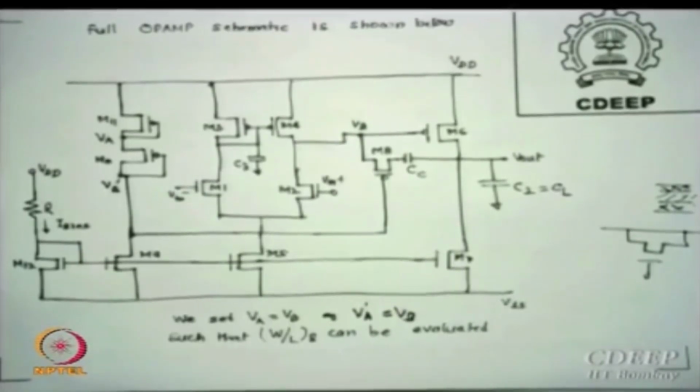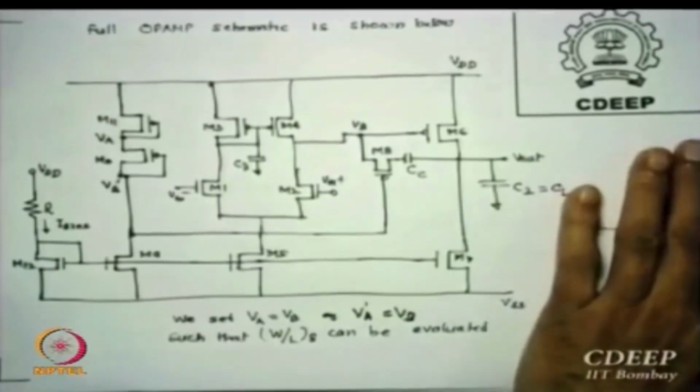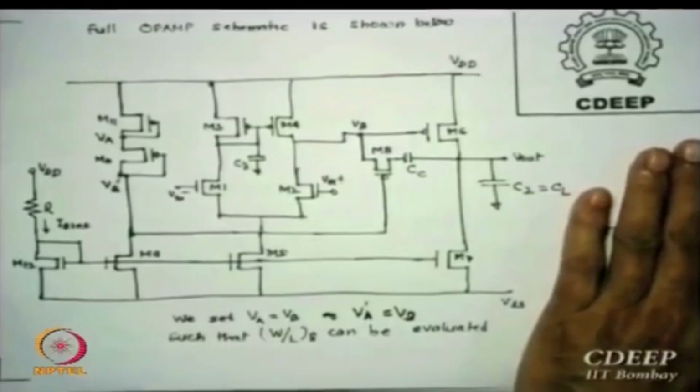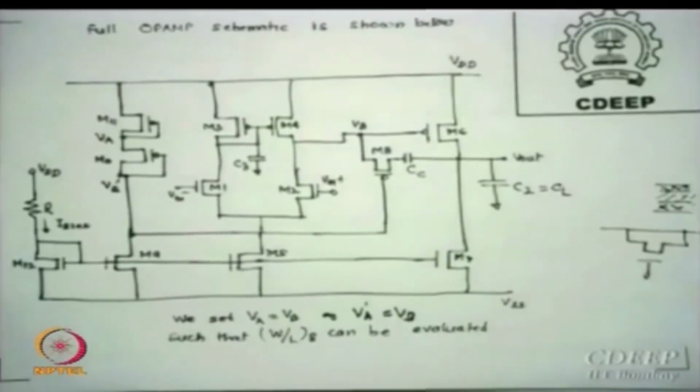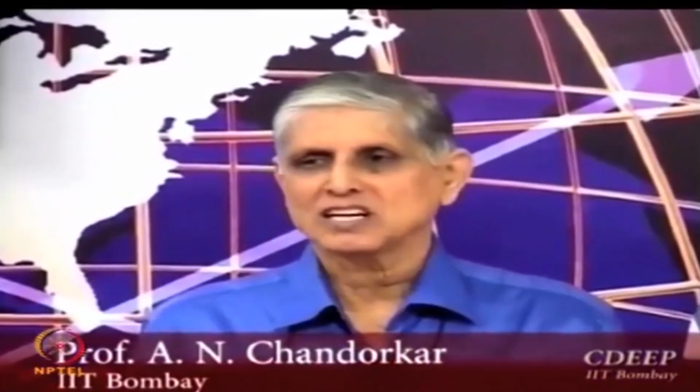So don't use the substrate, use the upper layer of poly and use another capacitor on that. The advantage there is these are independent of biases. Is that clear? These are like standard capacitors. Additional mask, additional money. But if the technology has that, then no additional mask because that process is anyway sitting there. Additionally, if you do anything, it costs additional money. You were asking yesterday, right, nobody wants to pay additional money. If you are paying, then might as well do it.